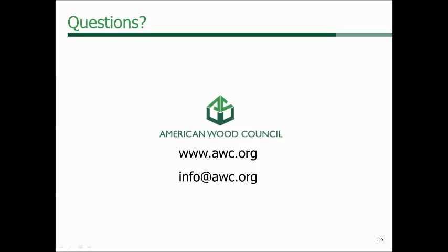Architectural and the premium appearance grades are likely going to be produced of higher quality lumber, which is probably going to have a higher cost associated with it. So if you're just specifying that you need a 22F beam, I would imagine the supplier would give you an industrial or a framing application, because that's probably what they have in stock.